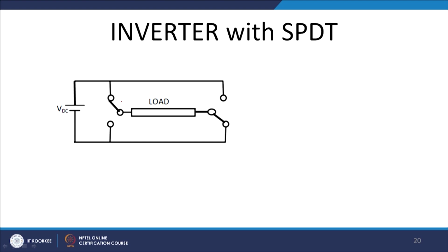This is the pole of the inverter, it has 2 terminals, 1 and 2, and these terminal points are A and B. The voltage AB will be connected to the DC bus voltage, the positive DC bus voltage, if point A is connected to point 1 and similarly point B is connected to point 2. So, we can change these points, and thus we can change the voltage across it.